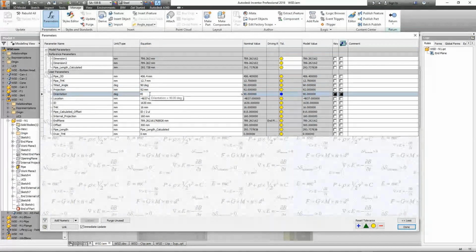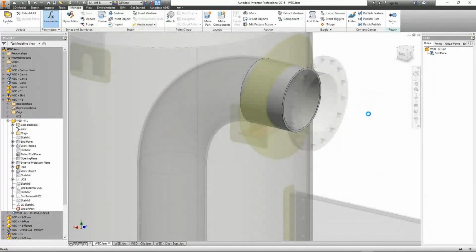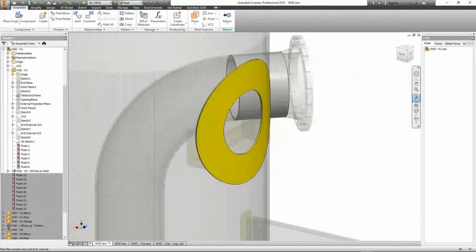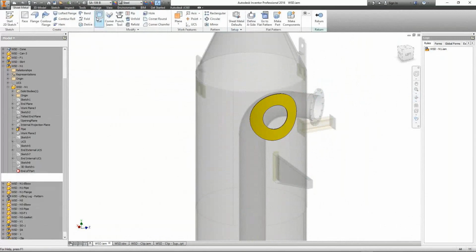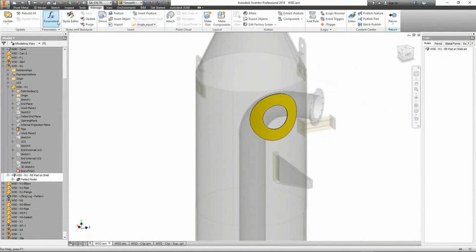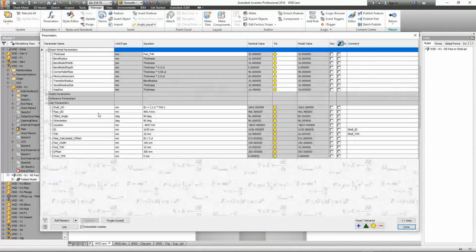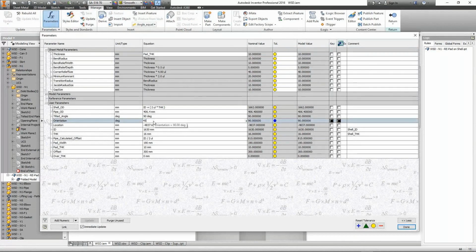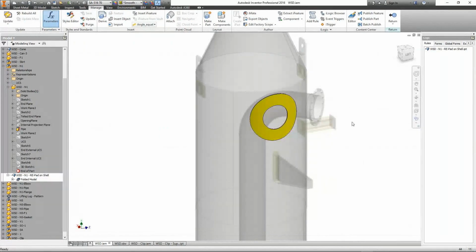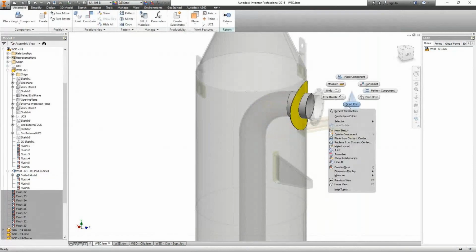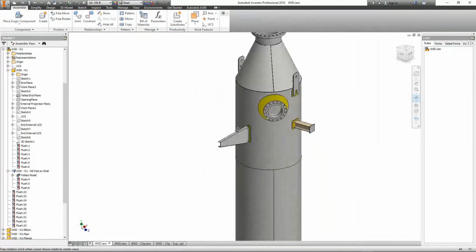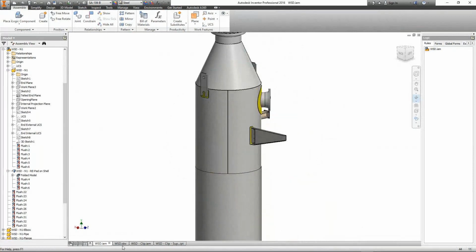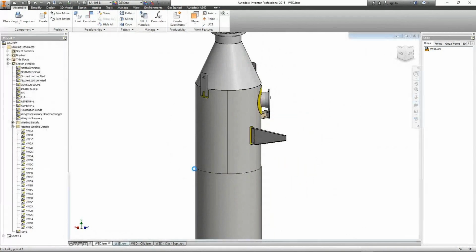Let's change the same for the wear plate. Okay, so here that's the nozzle, and we need to change the same value on the wear plate. So here, if we come to the orientation 45, you can figure that you have the ability to change it manually, but we don't recommend that. And when you come back to the drawing, it will be reflected.